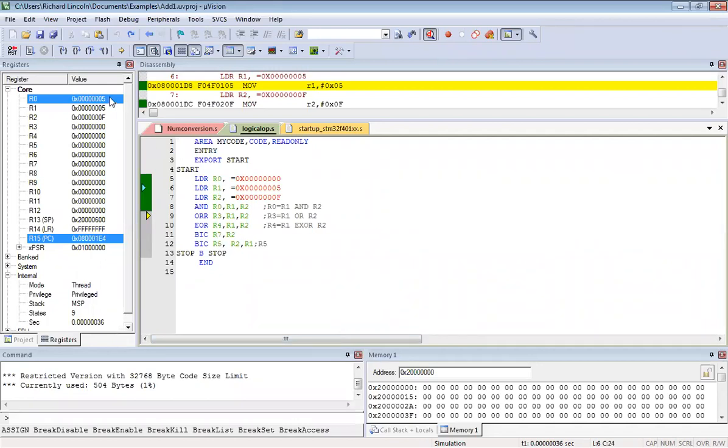Okay, so you should be able to see 5 in R0. If you take 0 0 0 0 and then 0 1 0 1, that gives you 5, and then 4 zeros, then 4 ones. So it's going to give you a high value when you AND only when there is 1 1, right? So 1 1 corresponds to only 5, which means the value is going to be 0 5 at the end, and that is going to be stored here in register R0.